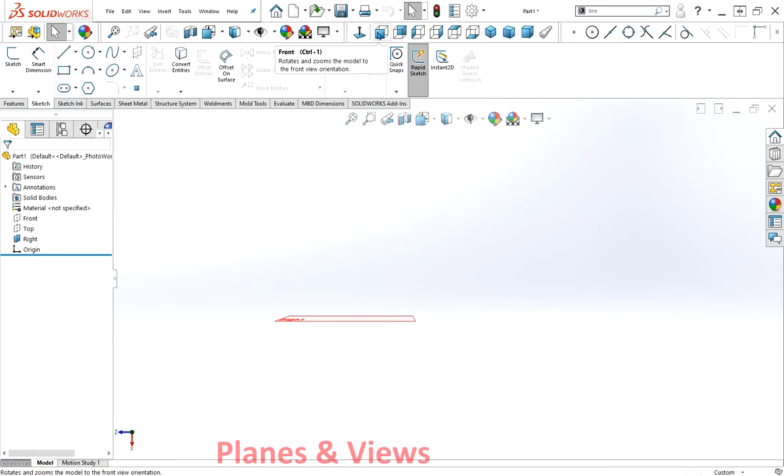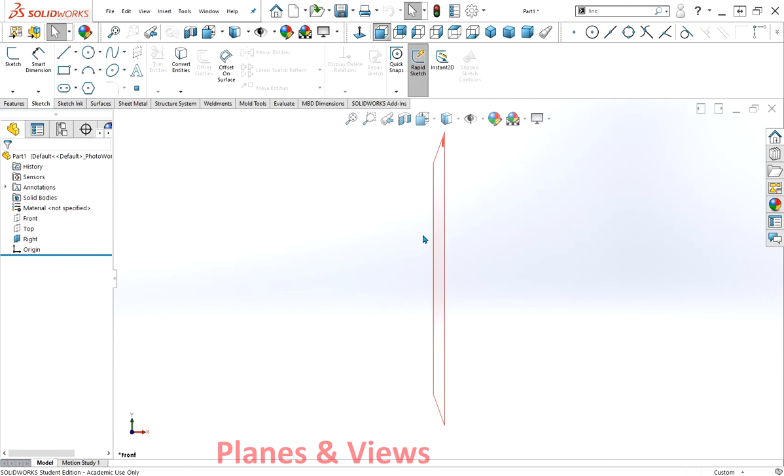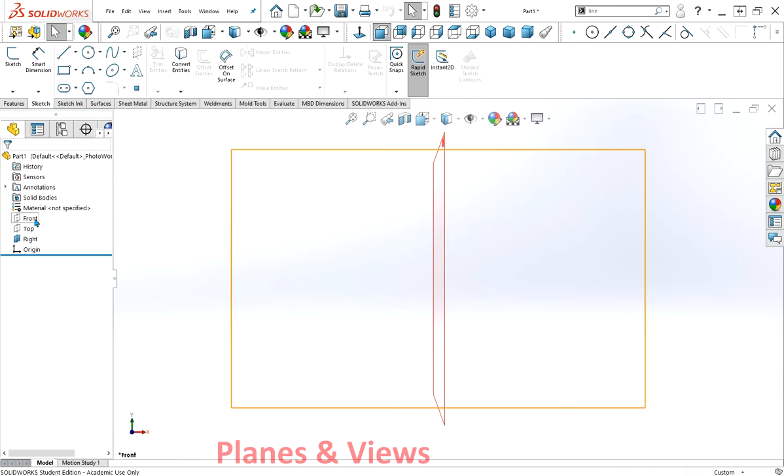Essentially though, get your head round the views. The front view, which ends up being the front view or in the drawing file, if you click on it, is actually looking at the front plane. So you need to work out what's the front view. You can change it, but it's far easier if you get it right from the outset.